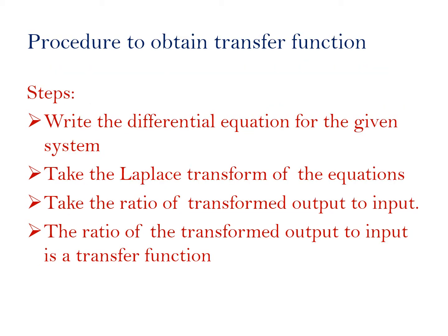Next, we are going to see procedure to obtain transfer function. What are the steps needed? The first one is write the differential equation for the given system. It may be a mathematical system, a physical system, mechanical system, that is rotational, pneumatic system, or hydraulic system. If any other system it may be, but for all the systems you have to write the differential equation,